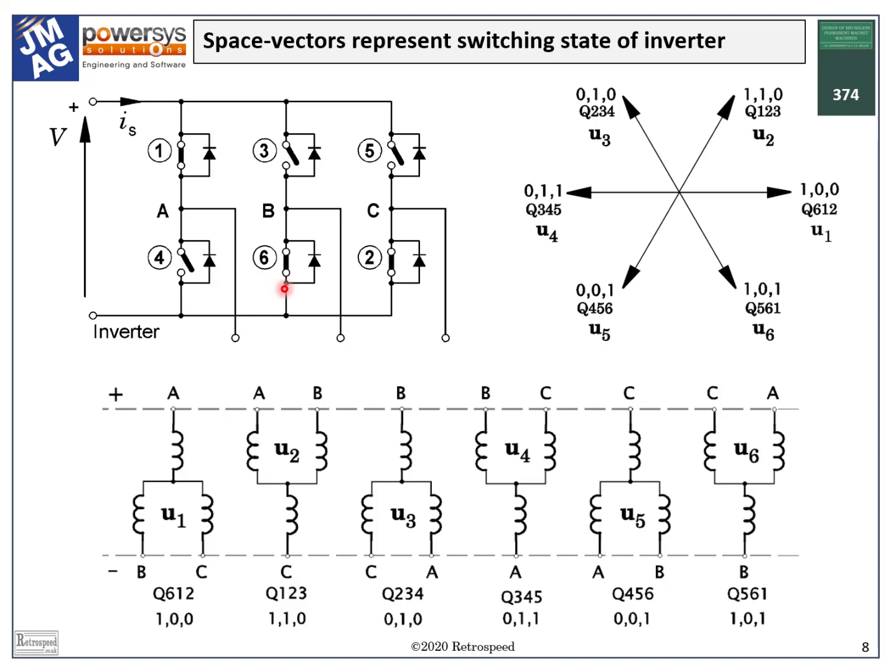Each of these states defines a voltage space vector at the motor terminals. Thus we can say that the space vector unites the theory of the motor with that of the inverter, not only at the power electronic switching frequency, usually a few kilohertz, but also at the lower frequencies of voltage and current variations on a timescale meaningful to the motor.